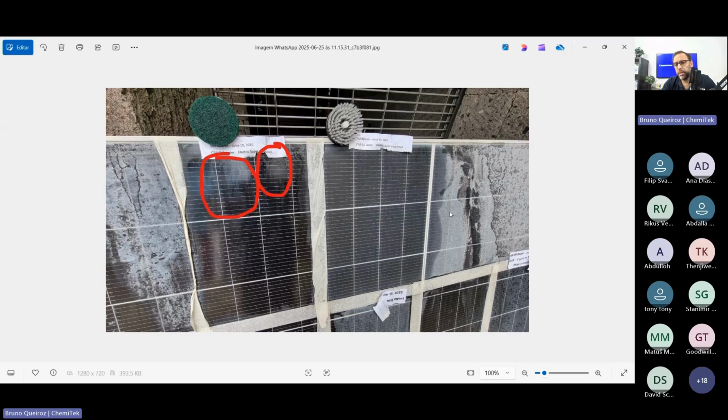These are panels taken from a rooftop where they were contaminated with water coming from the cooling towers, and where we were testing different brushes using the CRA. The one on the right was too soft to remove everything. The one on the left was effective, but it was too abrasive, and it was damaging the coating. So we recommended the customer to try nylon brush pads or walnut brush pads to make sure that the coating is not damaged by the cleaning process.